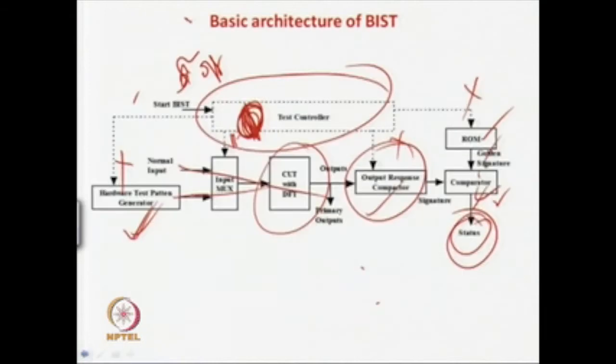But here one point you have to observe: somehow we have to make this ROM a very small size, and also the test pattern generator very small, because if you compare to an ATE, it also has a hardware pattern generator and a ROM which analyzes the response, but an ATE is a very big machine with a lot of memory power. So, you may not limit the number of test patterns; only the test pattern count is limited by the test time, because if you use too many test patterns then your test time will be higher, and so your ATE cost will increase.